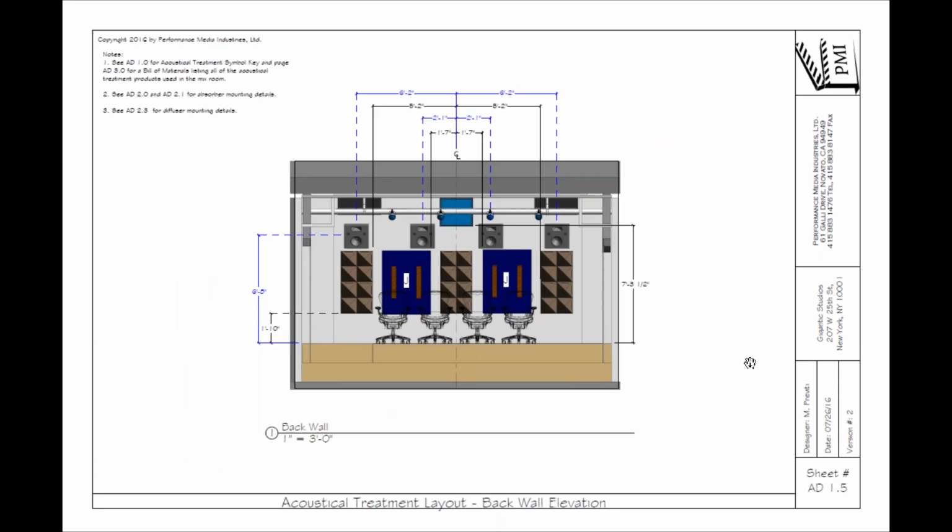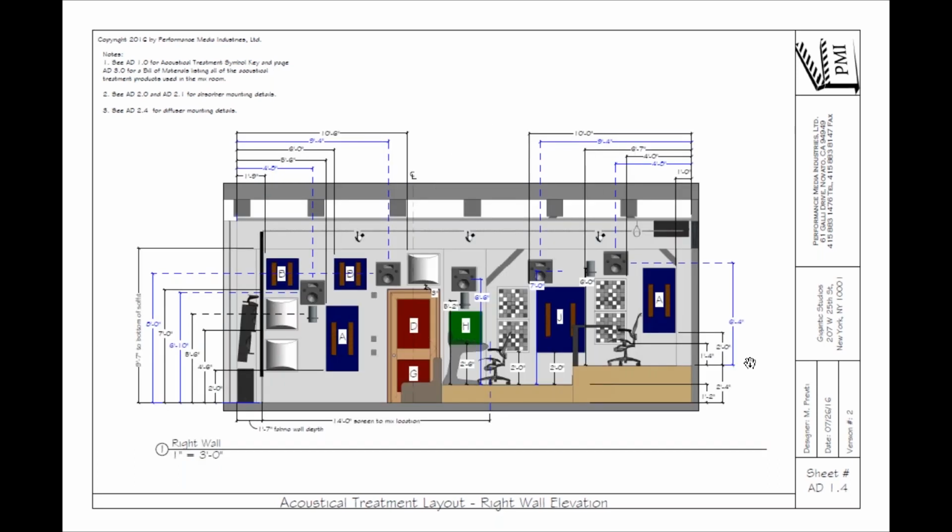Anthony, I'm sorry, something caught my eye, and I don't think this has come up in any of our conversations. That is a door in a mixing room, so I would assume that that's specifically made, or a certain thickness, or the hinges are super heavy duty, the handles are super heavy duty to stop that door from rattling. Well, more so, yes, but to stop the door from leaking sound. So this is a sound door, 300-pound slab on massive hinges with a big latch set, with massive gaskets all the way around it. So when you close the door, it's actually a magnet. It's a pair of dual magnetic gaskets.